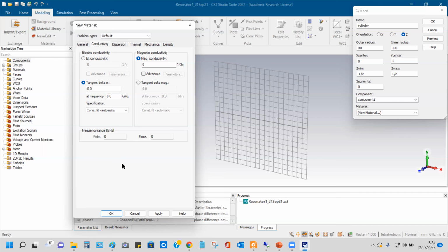You can talk of metamaterial, you can talk of metasurface, you can talk of anything that you want. Metamaterial, 3D metamaterial, 2D metamaterial, anything you want. What you are ultimately doing is playing with the effective dielectric constant, thereby modifying the propagation of the waves. Either you can absorb the waves, for example it can act as an absorber. What will happen is, indirectly you are playing with the L and C so that it becomes resonant there. That will trap the field, confine the field within the substrate, means within the structure. That is a kind of absorber, a metasurface absorber.